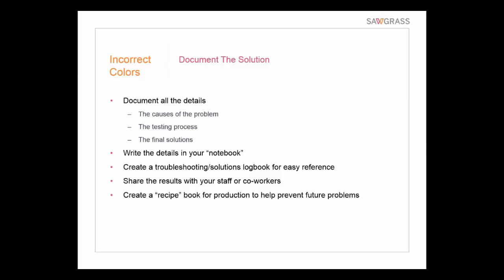There are other processes out there where they tell you to preheat something. For example, a shirt. If you're using a plastisol transfer, a lot of times they tell you to preheat the shirt for like 5 to 10 seconds before you apply it. Don't do that with sublimation. If you preheat something and then you actually lay on top of it a transfer, that transfer can start gassing right then. And then if you move the transfer, it can give you a blurry image. So you want to make sure that what you're pressing is cool to begin with.